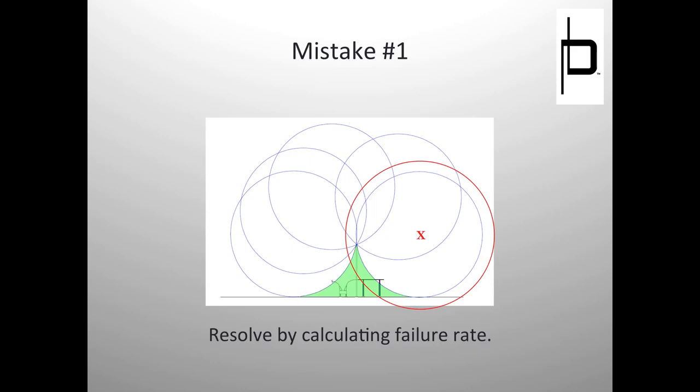But now, does that mean you're really only gonna have one failure every 400 years? I guess technically yes, but remember, there are other reasons for failure, other than the strike just getting into your shielding system. You could still have failure of your insulation. We talked about that. And this failure rate is based on lightning always striking the mast instead of striking your equipment, and we know that's not always true. So these things will actually reduce that.